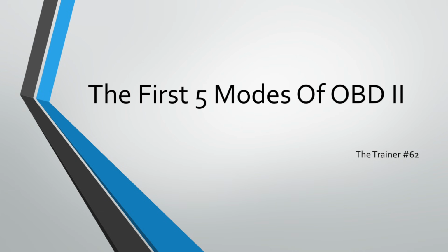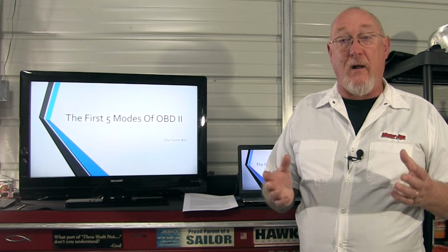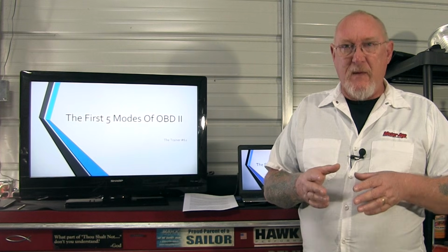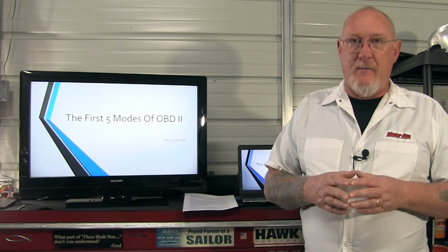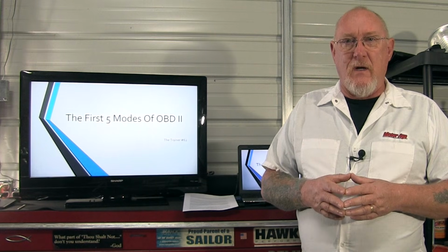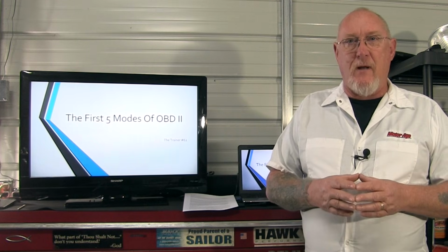Now, to help you unravel the complexities of OBD II, we're going to start this session by looking at the first 5 modes. Well, Pete, 5 modes, what are you talking about? Well, OBD II has a number of diagnostic options in it. Many of them you're already familiar with, but there are 10 total different modes in Global OBD II. All of them have some usefulness when it comes to diagnosing a problem.